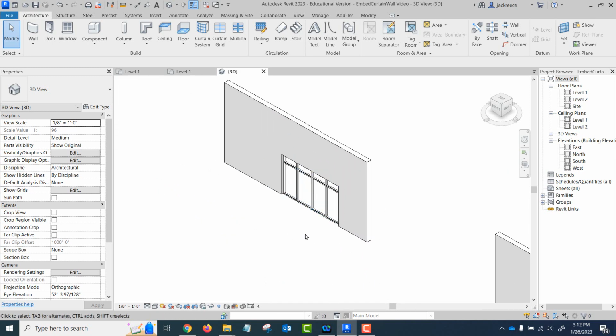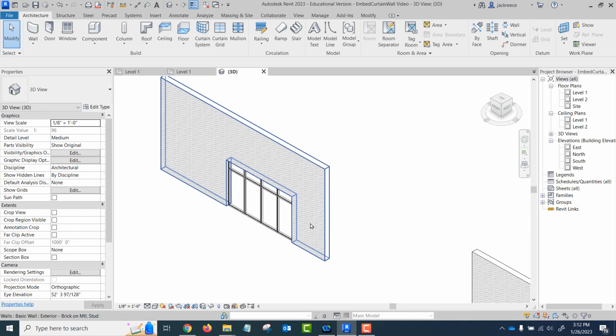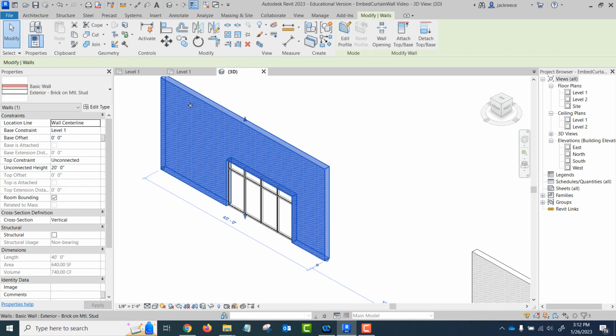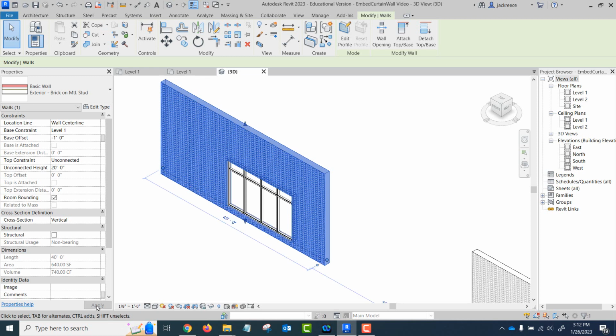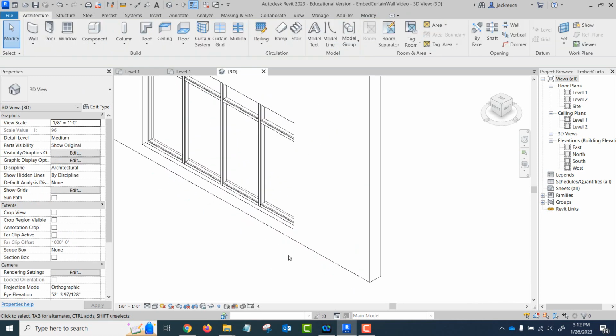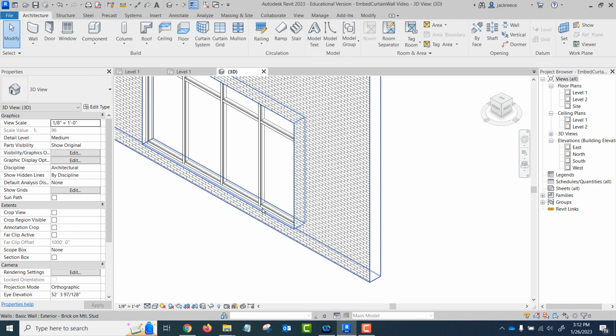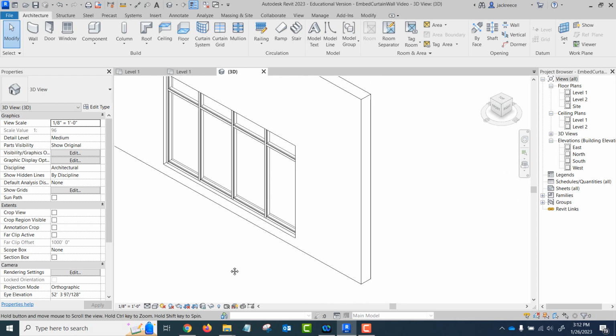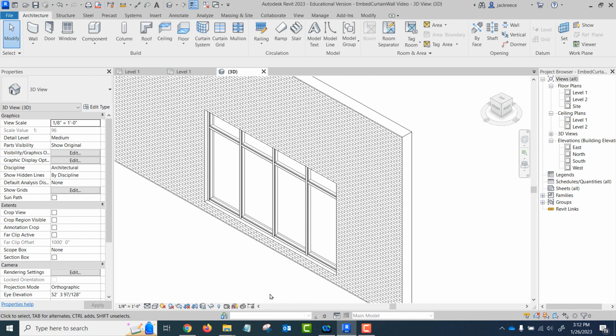Oh, I was looking at the other one. There we go. Okay, same kind of situation. It made an opening in the wall for itself. Now, if this wall, which this will be similar to your project, okay, so you can see my storefront wall is still at level 0, but the bottom of my brick wall is 1 foot down. Okay, and so that's how we would embed walls, and we can play with the lengths or the heights of these,